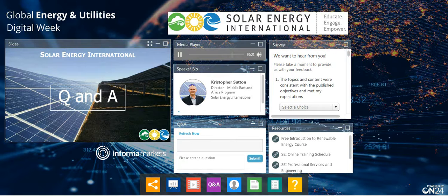Great, thanks. Our next question is about a specific application. They ask, what type of solar PV system would you use for a speed traffic camera and a street light? Okay, so that would be basically a standalone system. If you're looking at running a device like a traffic camera, for example, you want 24-hour use of that camera system, and so that's going to need to be battery-based.